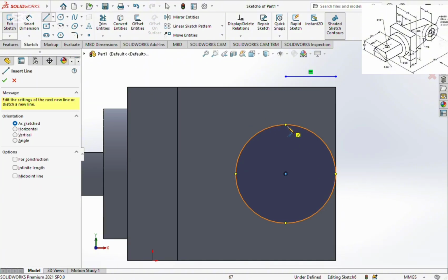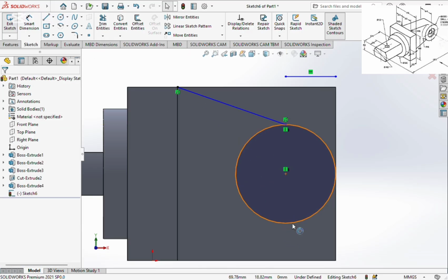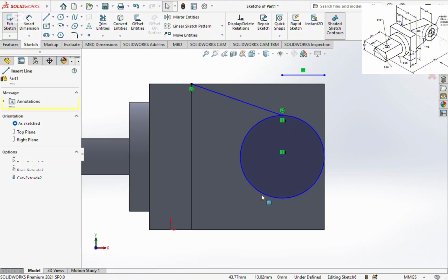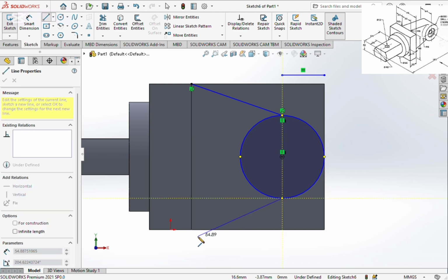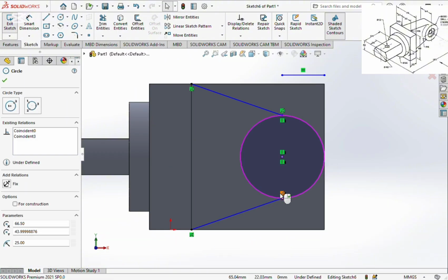Now, the next thing for me to do is to get a line that is tangential. So I start from this point. I use my line command from there to this edge. I escape. Then down also line command again. I type L, click L from your keyboard. Then from these down parts to this other edge here, click, then escape also.